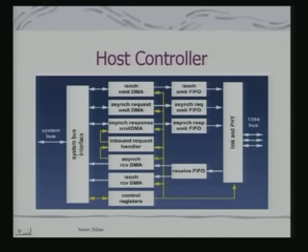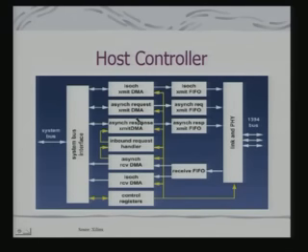Now, these FIFOs will obviously be connected to what? If you are looking at a host interface, they will all be connected to the various DMA channels. They will be connected to various DMA channels because this data has to be transferred to the memory area, so that the processor sitting inside the embedded system can make use of this data. We have not looked at this interface for other buses.